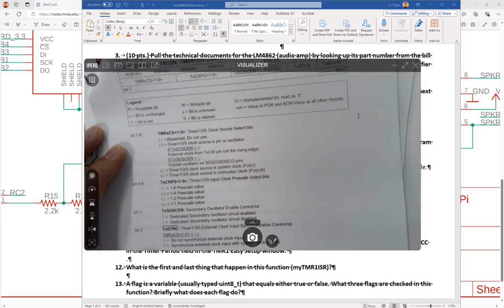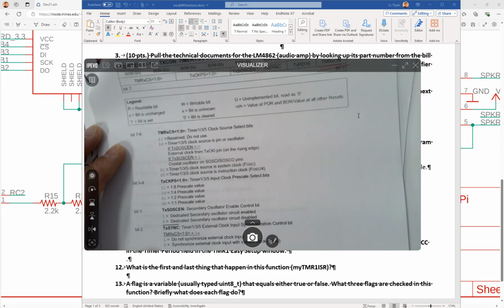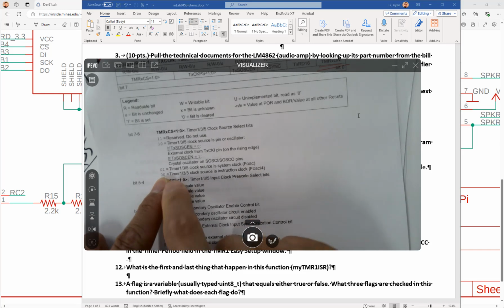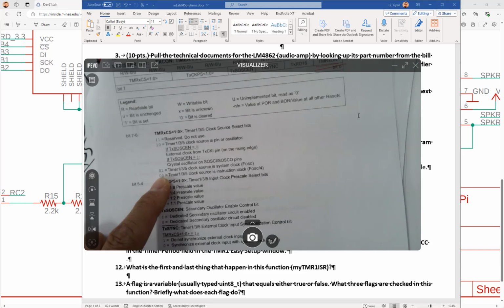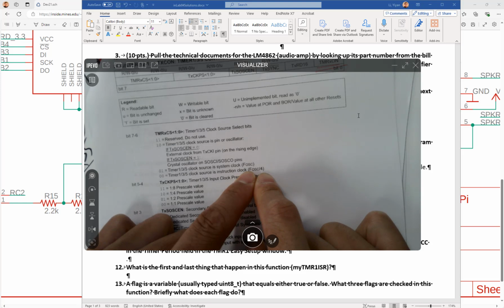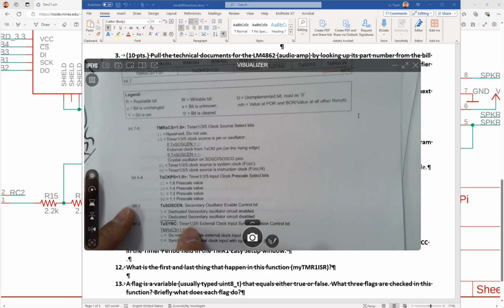So there's an original or main clock which we never actually used. It's 64 megahertz. So if you pick these 2 bits and give 0, 0 to it, it's giving you 64 divided by 4, which is 16 megahertz, the frequency we have been using for the main clock of the CPU, right? So what about the prescaler?